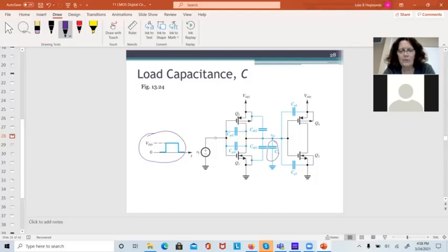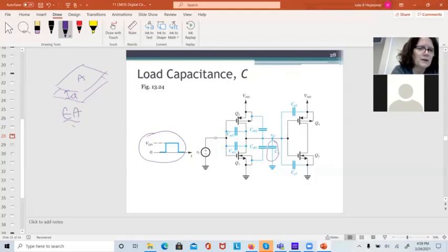And yeah, they all work together. What is the capacitance? Remember, for a parallel plate capacitor, let's see if I can draw this. So I've got a parallel plate capacitor. The capacitance is, this is the distance between the plates, it is the area of the plates. It's epsilon, which is a material property, A over D. And the A in this case is W times L.